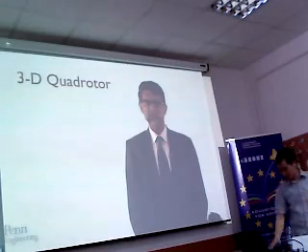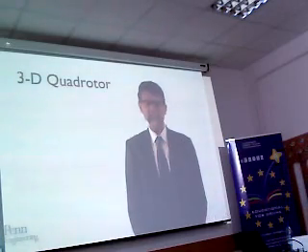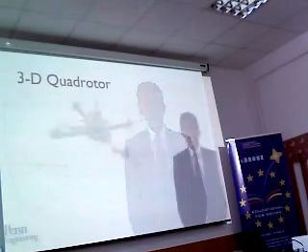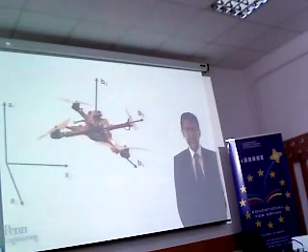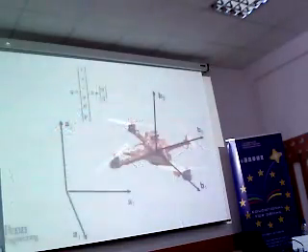controller for the problem. We have to turn our attention to the three-dimensional model with dynamics, and we'll talk about trajectory planning and control. We will recall that we attach a body fixed frame to the quadrotor, and then we have an inertial frame. The state of the quadrotor consists of position and orientation.